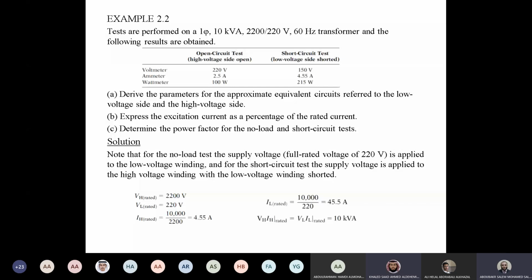Okay. And if you have a device, before connecting the device, you have to first check the rated voltage. For instance, here in Saudi Arabia, we have two different supplies, 110 and 220. If you bring supply 220 for a load of 110, it will be burned, it will be damaged. So you have to check the nameplate first. Okay.